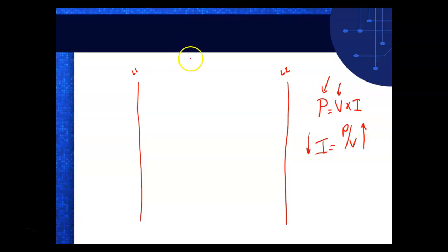So what we usually have up here is 3 phase, and they're called L1, L2, L3. Well, what problem? I'm calling my L1 and L2 over here. This might be 660 volts. This is not 660 volts. I'll show y'all the U.S. Steel prints. They call theirs PL1 and PL2. So it's going to be some variation of that. So normally what we do is we come over here and bring this through a transformer, and we step it down.